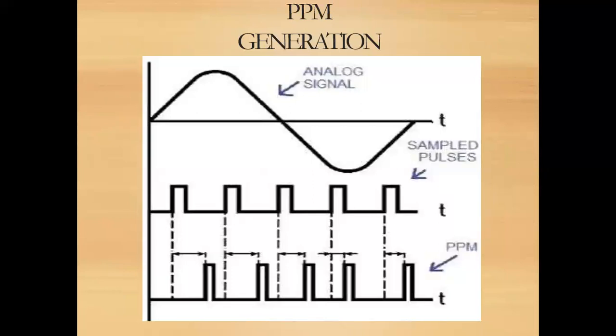What is meant by multivibrator? Actually, it will act as an oscillator. In this monostable multivibrator, there is only one stable state and the other state is a quasi-stable state. By these two states, wherever we require, we will be getting our output like pulse position modulation. As PWM is given as reference, from the PWM we will be achieving our PPM.